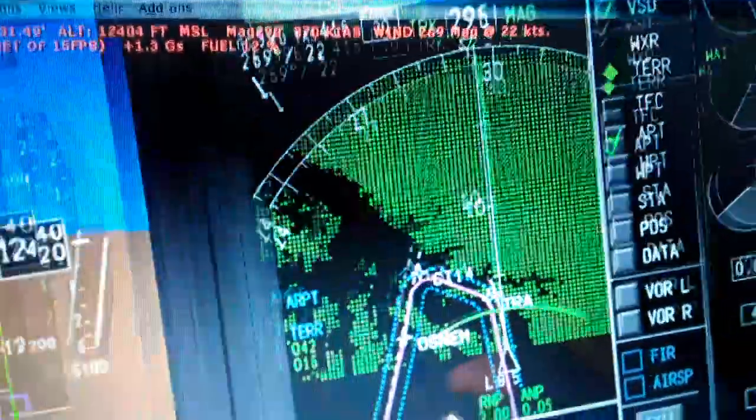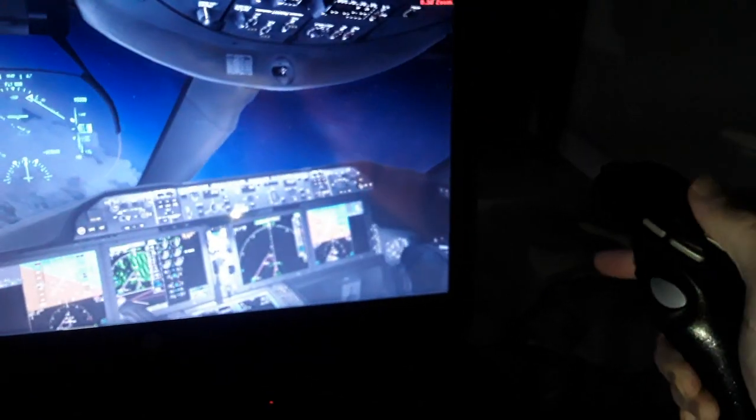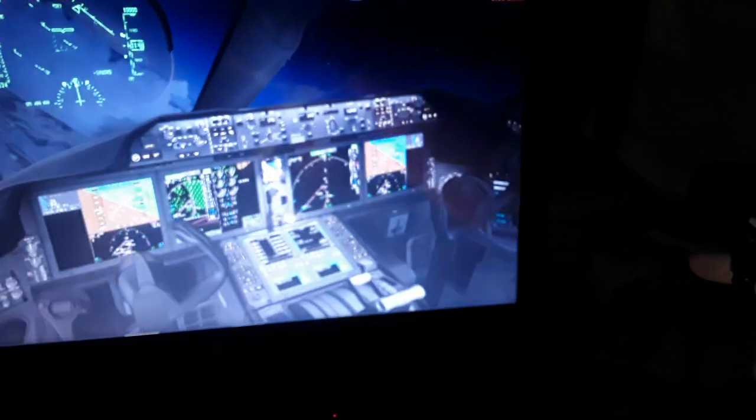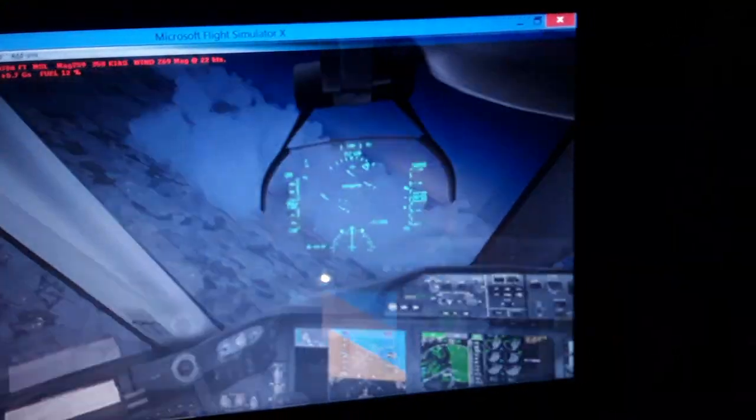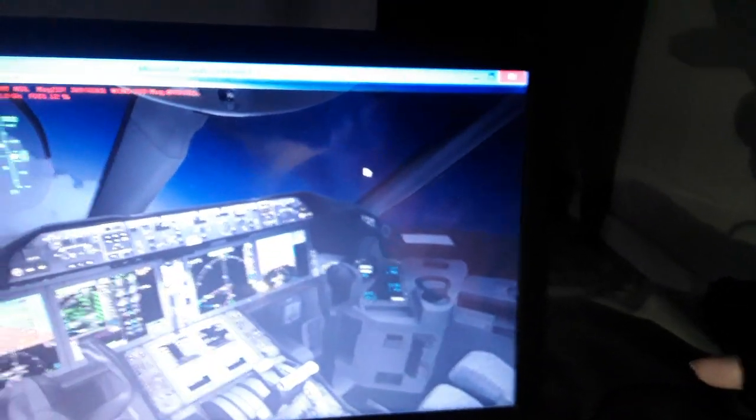We need to initiate the turn now, as you can see, crossing the waypoints here. So we make the turn very fast. Keep descending also, and use a little bit of left rudder actually, not right. So we increase the rate of turn over here as we descend. Make a steeper turn. And we need 3 more minutes to reach the runway over here.